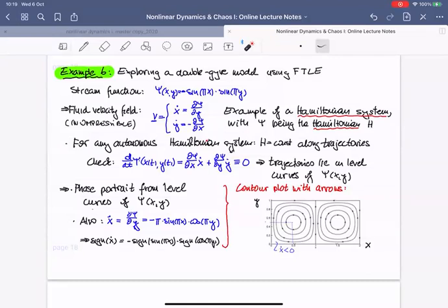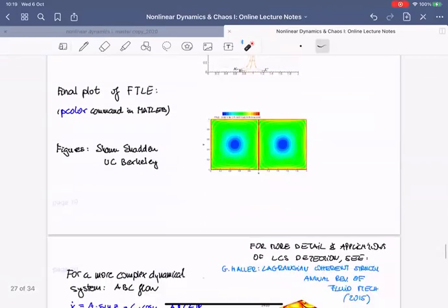But when it comes to their own work, they say, hey, what better tool can you have? I'm still going to plot the instantaneous streamlines, and they should be really close to what the fluid does. Well, guess what? No. If the fluid is very complicated, just highly time dependent, they have very little to do with each other. You can see that by doing flow visualization experiments, just throwing anything in the fluid: it's not going to follow the streamlines. So then these methods really become important.